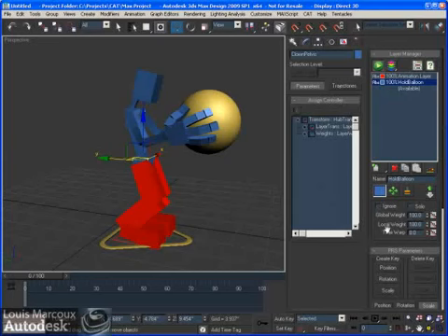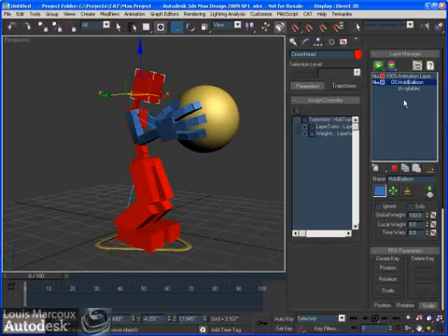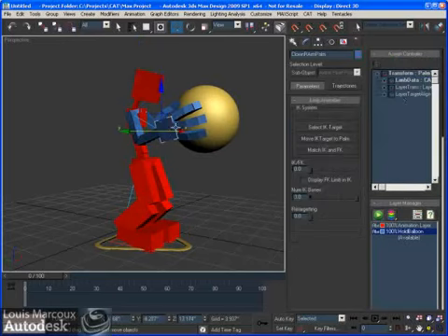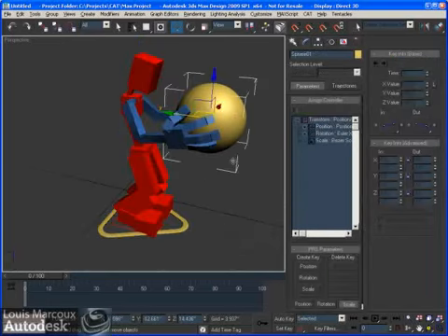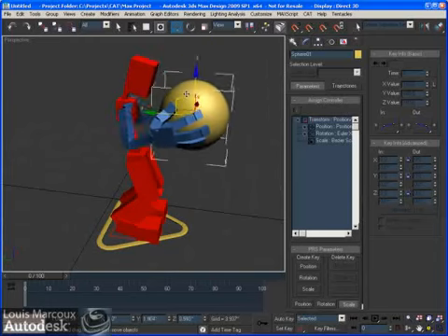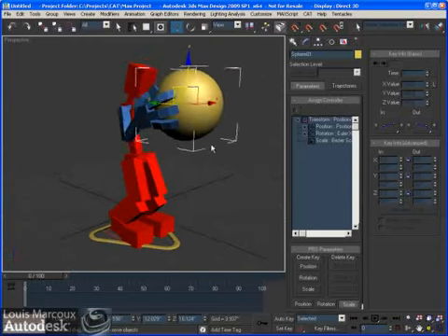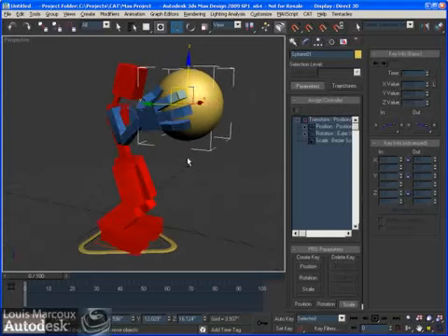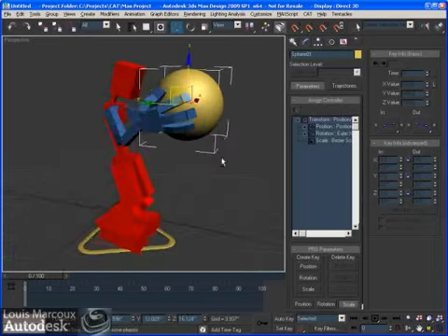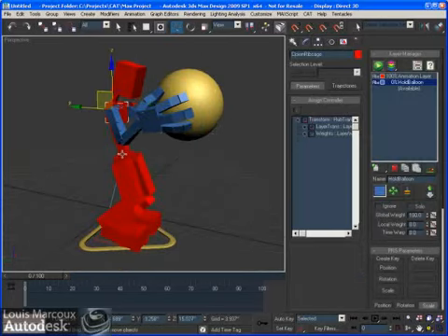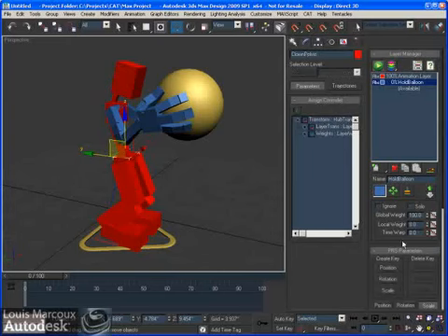So I'm going to grab the pelvis here, global weight to 0, the hub here, global weight to 0, same thing for the head here, global weight to 0. So now I can see that this layer itself will affect the arms, and it's set to 100% for the arms, so I can move this target around. And you see that this is the effect. The reason why I want to show you this is that now I'll grab the pelvis and make it back to 100% and 100% so that this layer does influence the whole upper body.